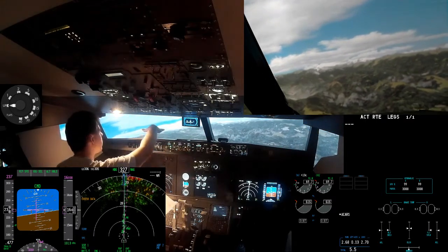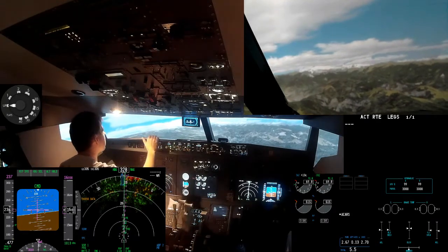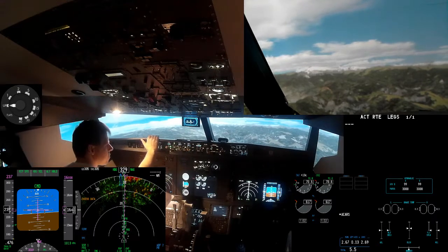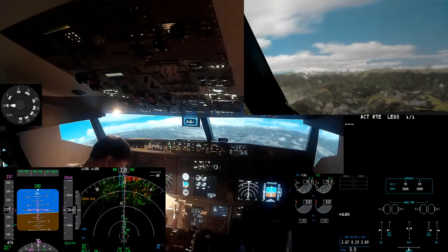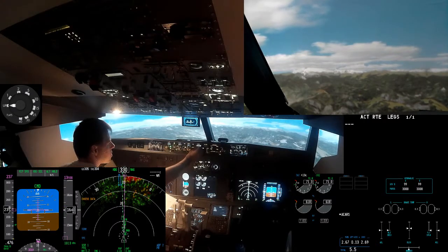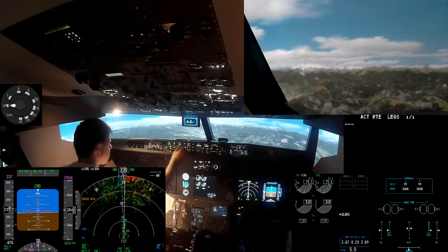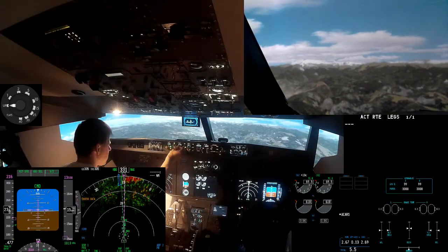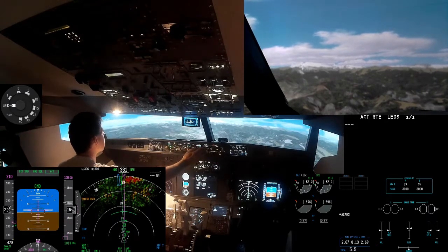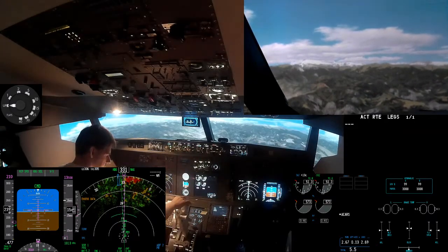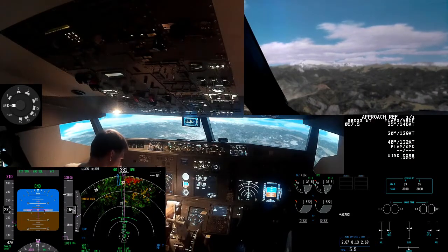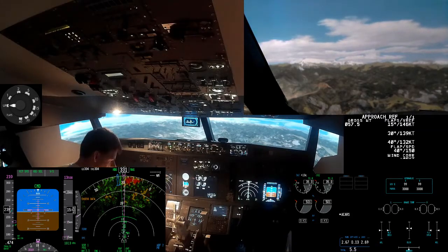We can see in front of us the valley. We don't have any major clouds in there, so no fog. And we can descend to 13,500 feet. And we'll start reducing speed to 210 for the first. Approach speed is set with 150.